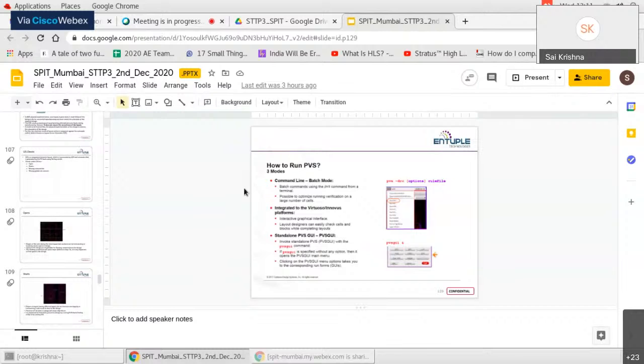After that, you come to CTS, which is meant to make sure all the clock reaches all the sequential cells approximately at the same time. So you will be using only clock buffers and clock inverters. Build a clock tree spec, and accordingly build your actual clock tree. So once clock tree is built, you will check for congestion, timing, area, power. This time timing will be for both setup and hold, and then any violation post CTS optimization.